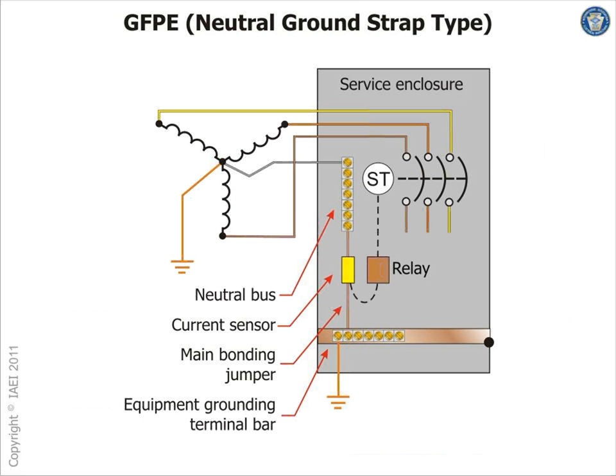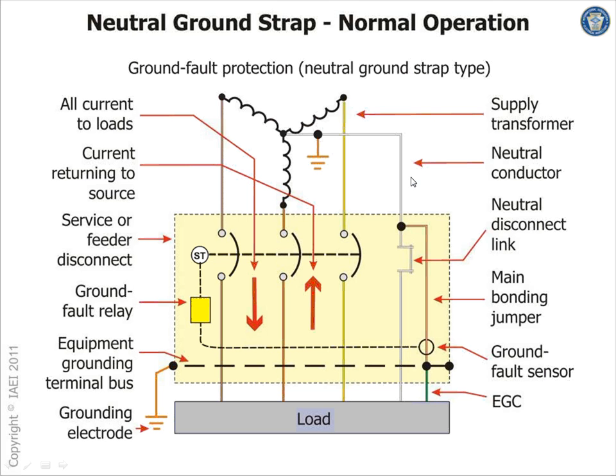Objectionable current at the second building. This is ground fault protection. You guys are familiar with that one, 1000 amp, 480/277. I thought just to throw in a monitoring system, relay monitors. Here's another example of ground fault protection required on every solidly grounded system, 1000 amp or more. You have to have ground fault protection.